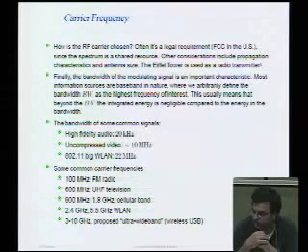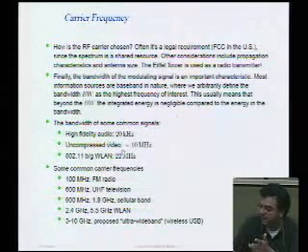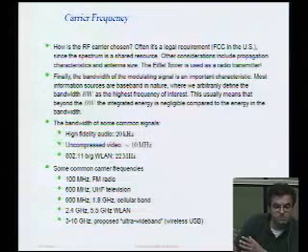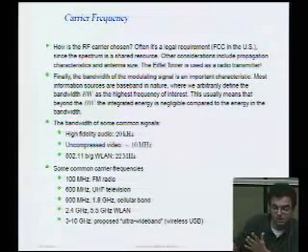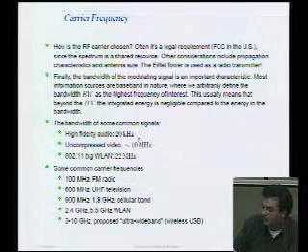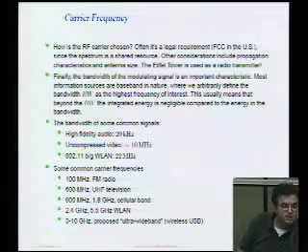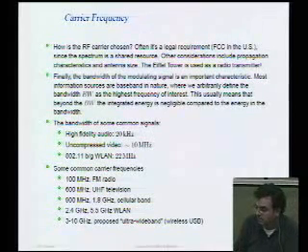And I put down some numbers here. High fidelity audio is about 20 kilohertz of raw bandwidth. Now if you modulate that linearly onto a carrier, the bandwidth doesn't change. So if I just AM modulate, bandwidth's about the same. If I do some kind of nonlinear modulation like FM, there's actually a big bandwidth expansion. I need about 10 times more bandwidth. To send video, you need about a megahertz to 10 megahertz, depending on what kind of quality we're talking about and how big that little screen is on your computer. For instance, wireless LAN uses about 22 megahertz. So in theory, you could send video signals through that.